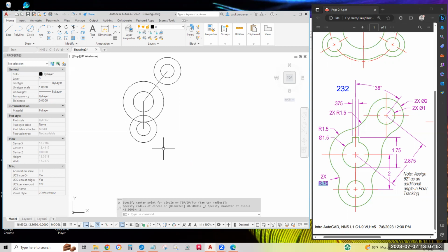So we'll launch trim. No, we'll launch fillet. Radius is 0 for a start for scratch new drawing. Click radius. Let's set the radius to 1.5 and hit enter. And click to place an arc there. Enter to invoke the last used command.